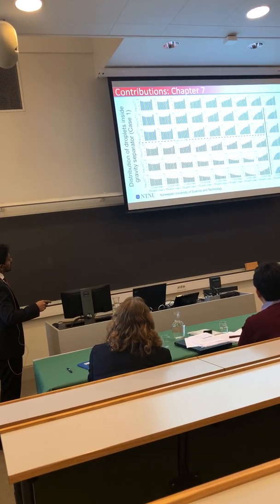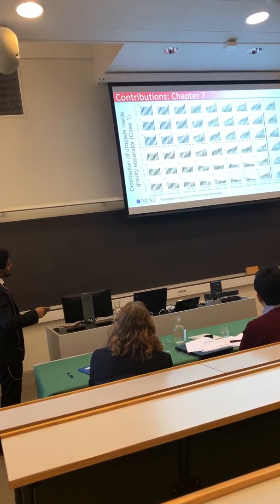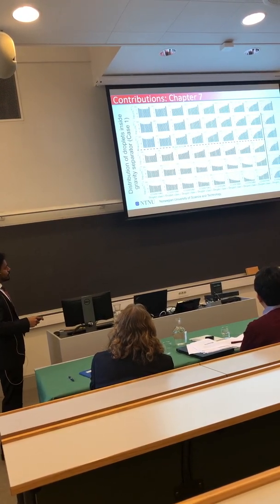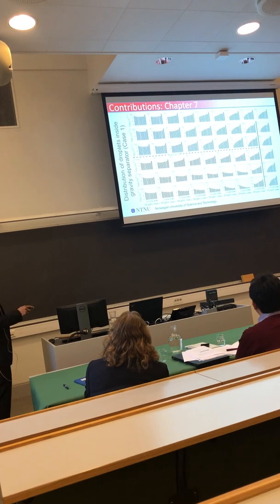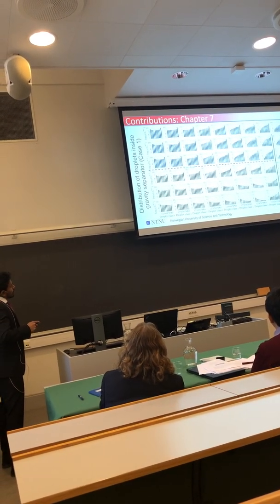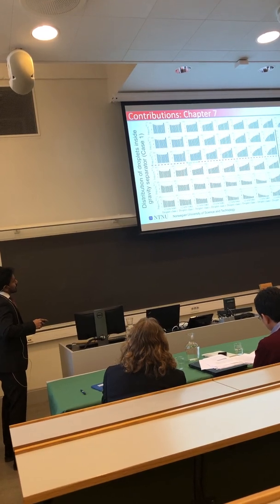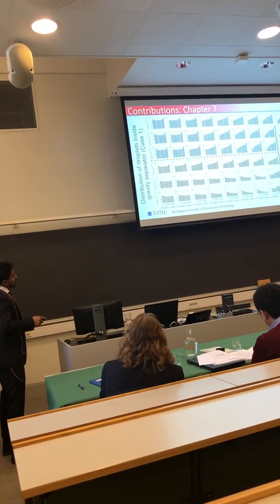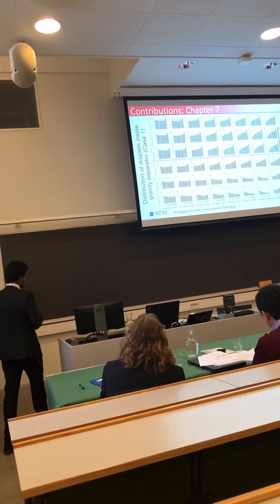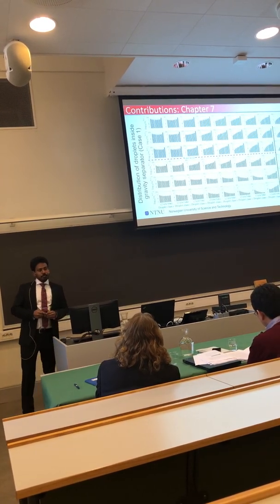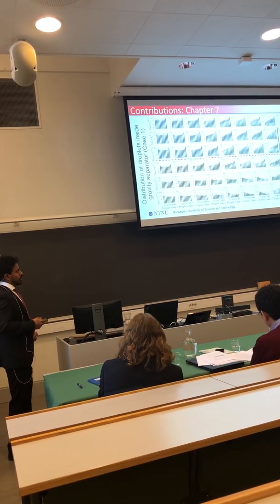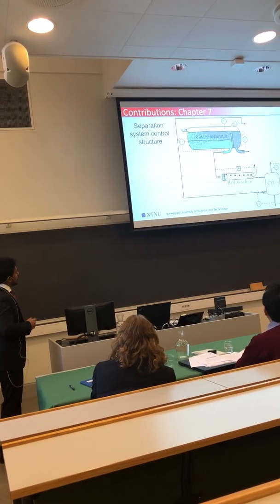And as it reaches here, the coalescence is still working. That's why you see that the lowest number goes down further, even though there is no non-convective flow in this part. The oil is going further down quite a lot, and towards the end it starts to accumulate because in these areas we do not consider non-convective flow, because the convective flows are too strong for the effect of non-convective flows to be any more important.